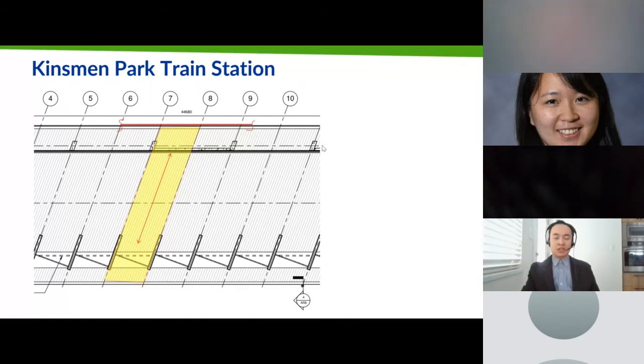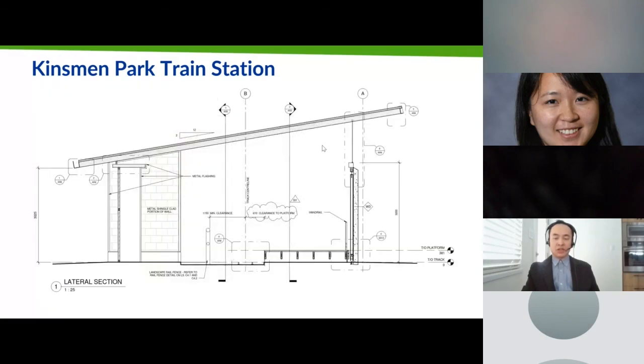And it's basically acting as a stiffening transfer beam that picks up the north edge of the CLT panel and then redirects or transfers loads to the stiffer points of the CLT that are cantilevering past the precast concrete columns. And we're essentially creating a hybrid structure that has timber and steel in it. So here's a section through the train station showing these elements.